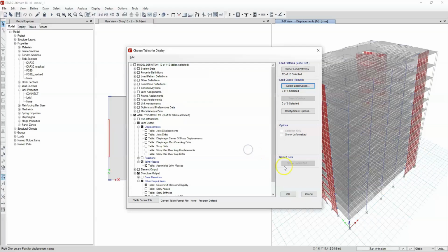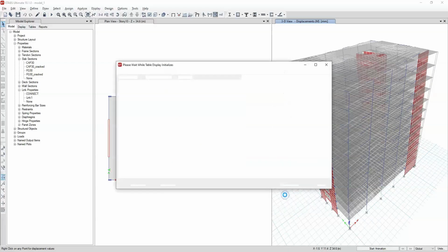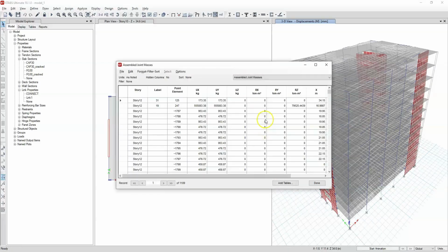and that we are going to use to discover, in an initial phase, the rotations of each story and the displacements of each story, and by using the information, establish relative displacements between stories, which in a way, allow us to account for the stiffness of each story, or calculate the stiffness of each story. We are going to use Excel again. These tables to Excel, that is what we are going to do.